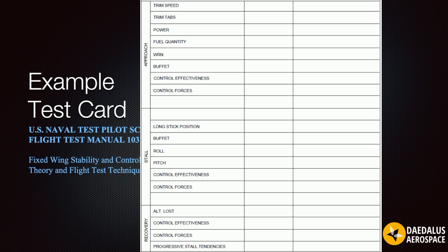You could record a lot of stall test data using this test card, but will you fly the stall test procedure correctly? That depends on the flight test brief and a shared understanding of the defined stall test technique to be flown, because, as you can see, there's no procedural information listed as far as exactly how the flight test technique should be flown. That would be expected to be briefed before the flight and documented somewhere else.